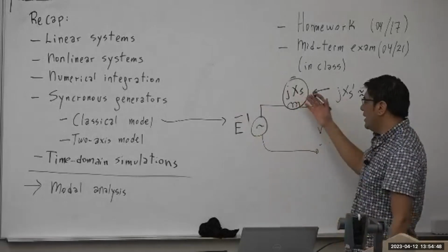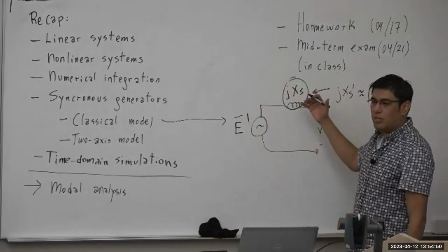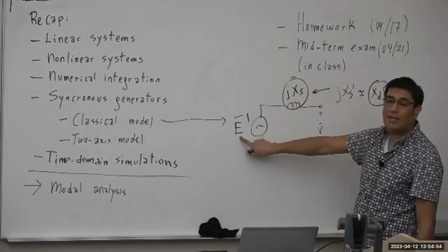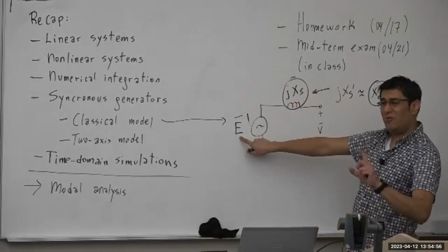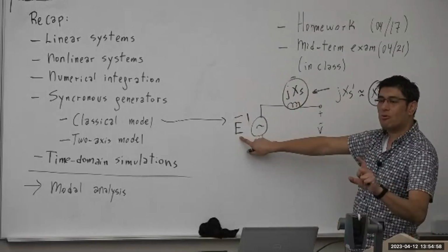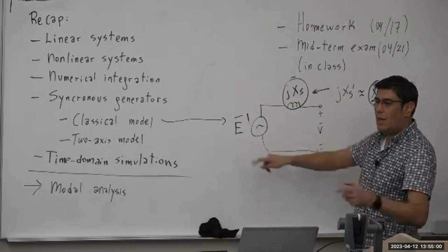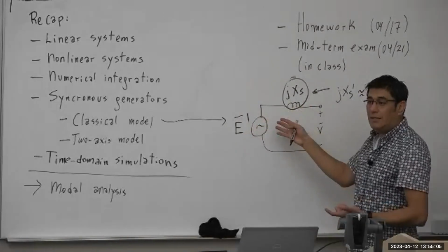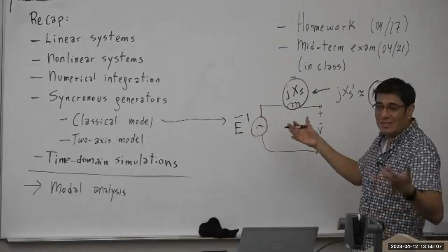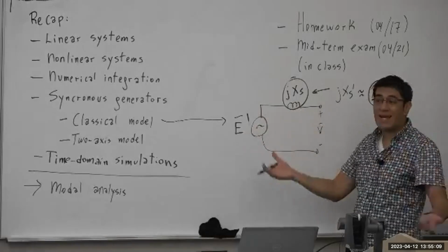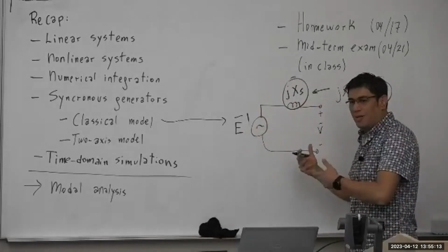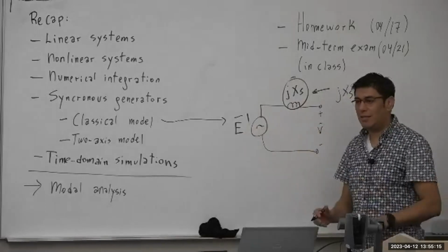The procedure is right at the short circuit, when you have high current, then you calculate that internal voltage and you assume the magnitude of that voltage remains fixed. I didn't want to go into those details because we don't use the classical model today for any practical analysis of any system. But to be proper, that is actually the classical model.